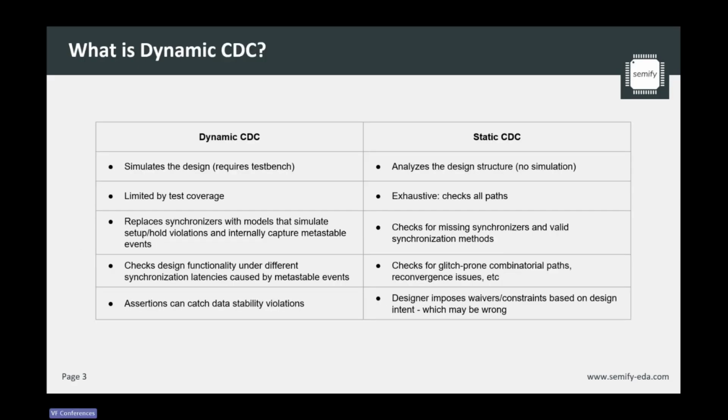So what actually is dynamic CDC? It's essentially verification that's aimed at applying metastable stimulus dynamically in a test bench environment to a simulation where this metastability is injected into CDC crossings so that the changes in synchronization latency at the data output of the synchronizer can be observed. That's a little bit of a word soup.